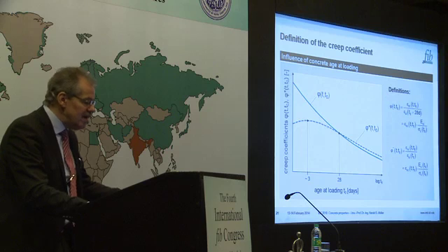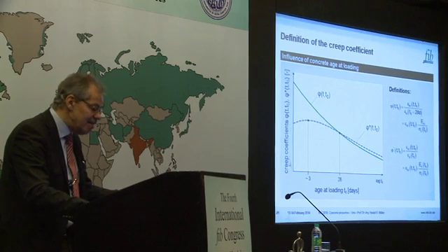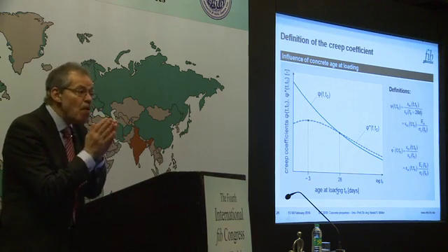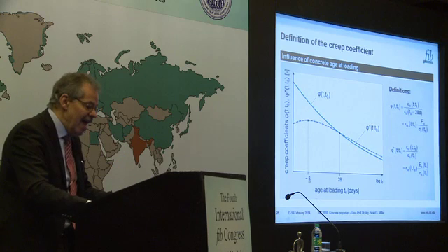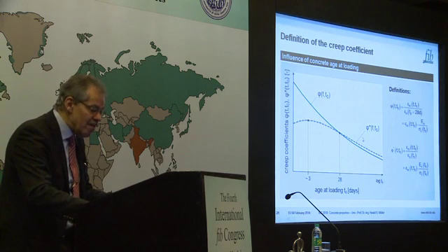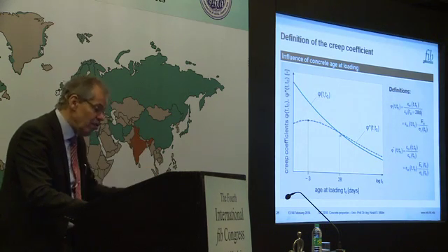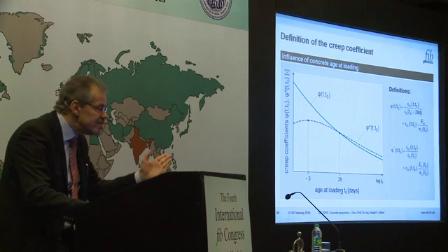The explanation is given on the left-hand diagram. Creep coefficient over age of loading, the most decisive parameter. And if you plot now for the same concrete, the creep coefficient of ACI and that of FIB, you see the difference. There's first of all no difference for the age 28 days, which is clear.